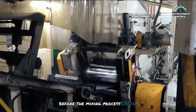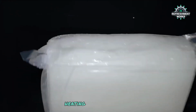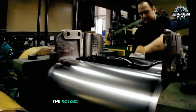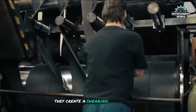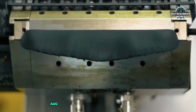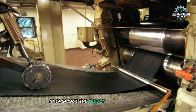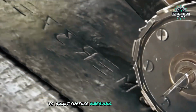Before the mixing process begins, the mixing chamber is heated to raise the temperature of the rubber compound. Heating softens the rubber, making it more malleable and easier to blend with the other ingredients. Once the chamber is heated, the rotors start rotating in opposite directions. As the rotors move, they create a shearing and kneading action within the mixing chamber. This action causes the rubber and other ingredients to blend together. There are different formulations for different parts of the tire, however. In each case, the result is gummy rubber dough, which machinery rolls into sheets to await further kneading and processing.